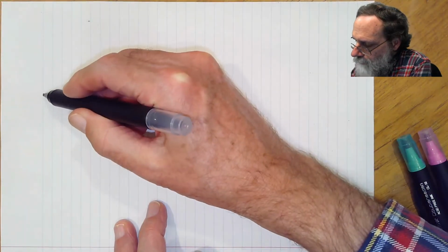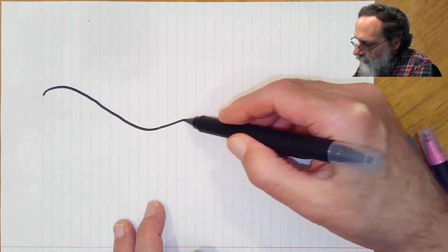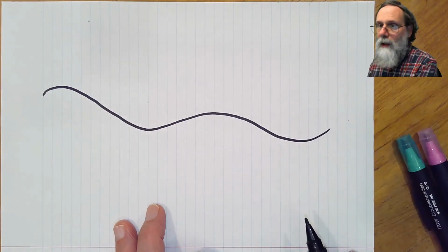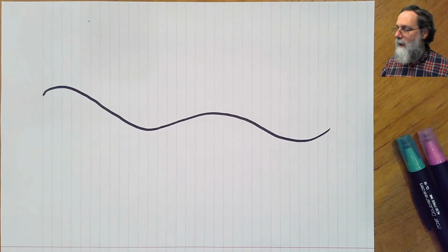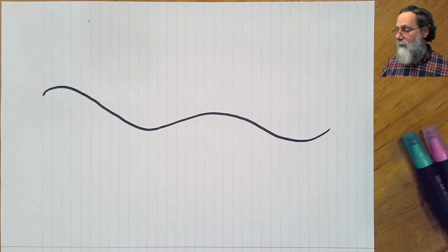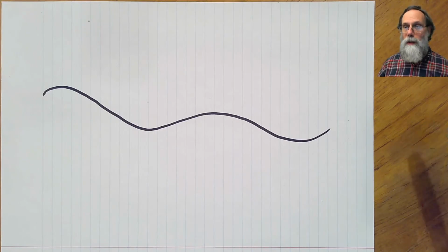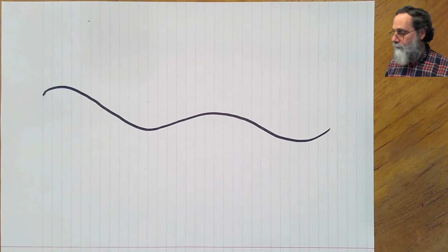We've got our slowly changing analog signal. And by slowly changing, I mean that the highest frequency involved in this analog signal is less than half our pulse width modulation frequency. And that's something that we need in order to be able to represent anything in discrete time. It's the Nyquist theorem. You can't represent frequencies higher than half your sampling frequency.